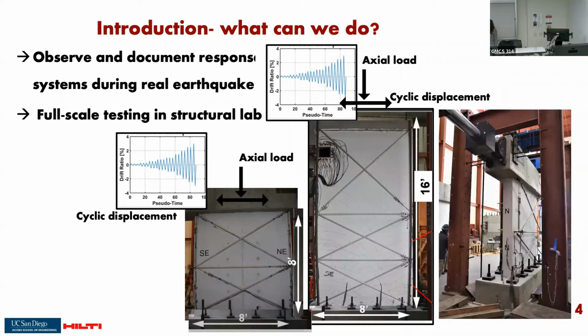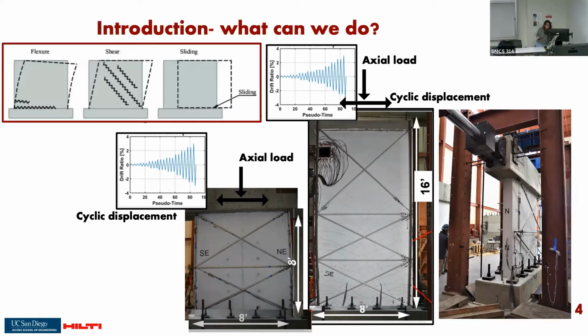One here is called the slender wall because if you take the ratio between the height over the length, you get a value of 2. And walls like these are called slender walls. They usually respond during earthquakes with a specific type of damage, in a flexural way. If you imagine this wall during an earthquake, you will get a majority of damage like this: cracks that are almost horizontal.